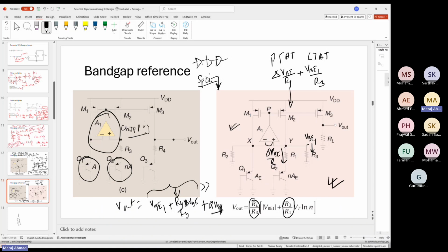It is very specific to design. Like this band gap, if it is used in an LDO, you don't need chopping. But if there is an application in which LDO noise should be very low, then this needs the flicker noise of all this and noise of these transistors to be taken care of.